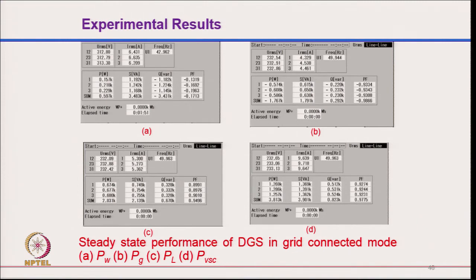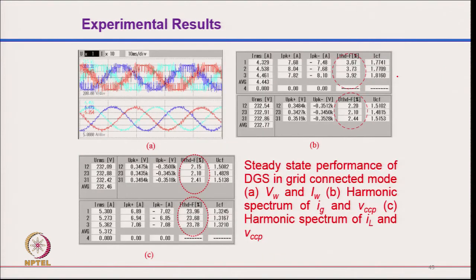So, you have the grid voltage, grid current and grid power, with the P and Q of the grid and the power factor of the grid. Even with a distorted voltage, you still have balanced sinusoidal current, and you have a quite good THD of the voltage and current. When the load current THD is quite high, the grid current THD is still typically less than 5%.